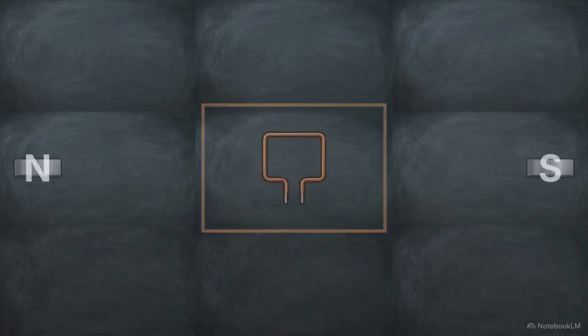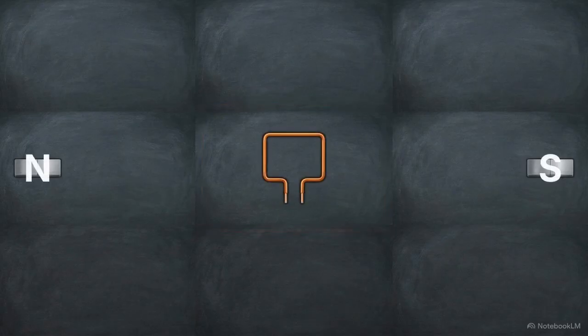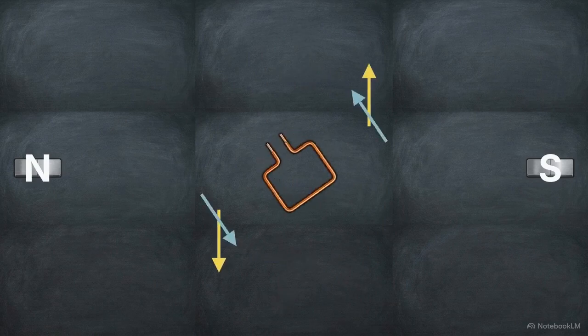A straight wire produces a single linear push. To achieve continuous rotation, we bend the wire into a rectangular loop and place it between the permanent magnetic poles. Current flows down one side of the loop and up the other. Because the current directions are reversed, the motor effect pushes the left side of the coil up while pushing the right side down. This creates a torque that spins the coil.